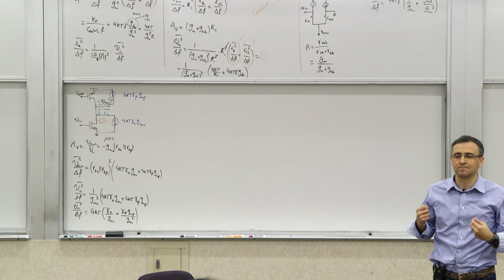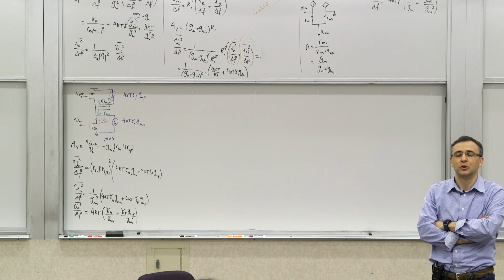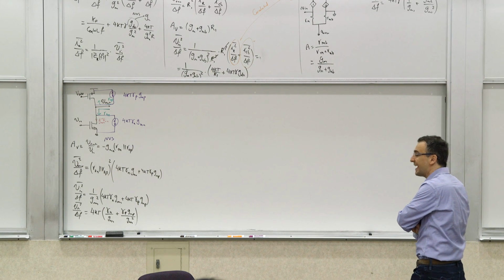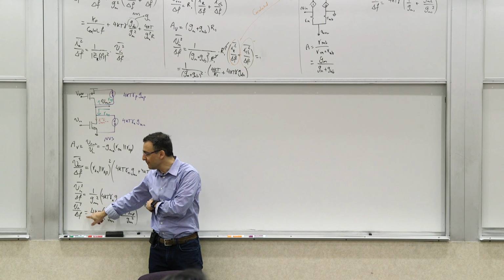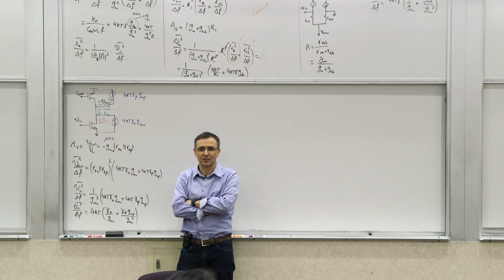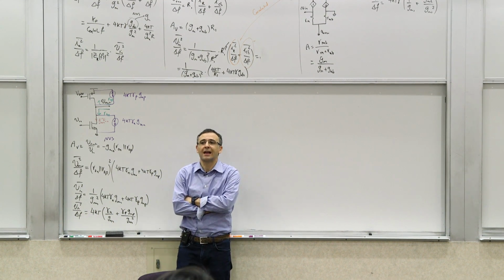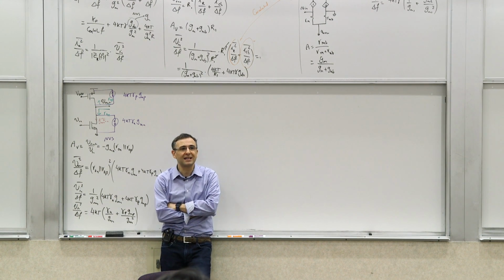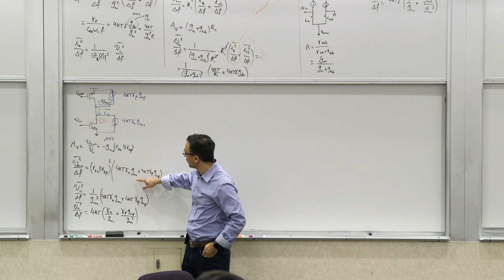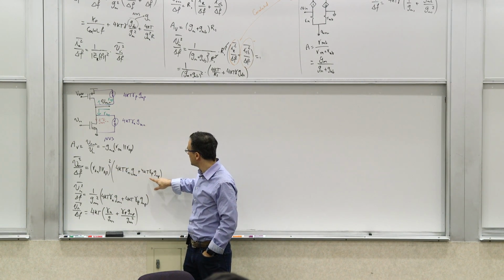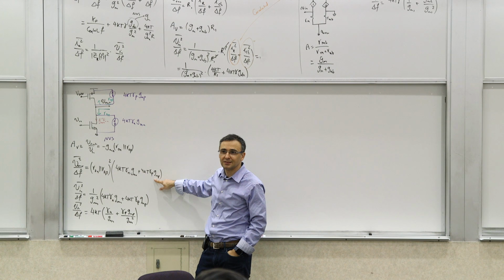If you increase GMN, you're also increasing your gain. GMN affects the gain, but GMP doesn't. And it helps because it's the input referred noise, so it gets scaled by the gain. Another way of saying it is that you get more signal at the output. Your signal becomes stronger. Because if you look at the output noise, increasing both GMN and GMP seems to have the same effect.